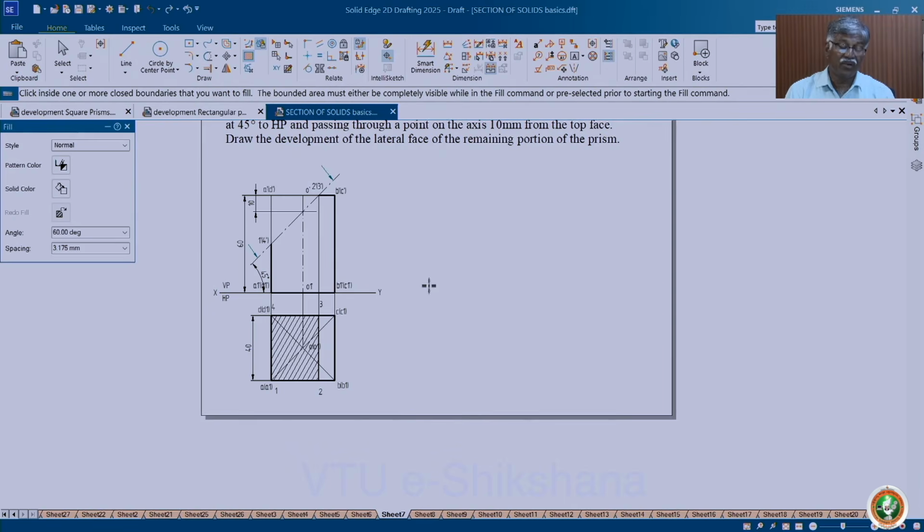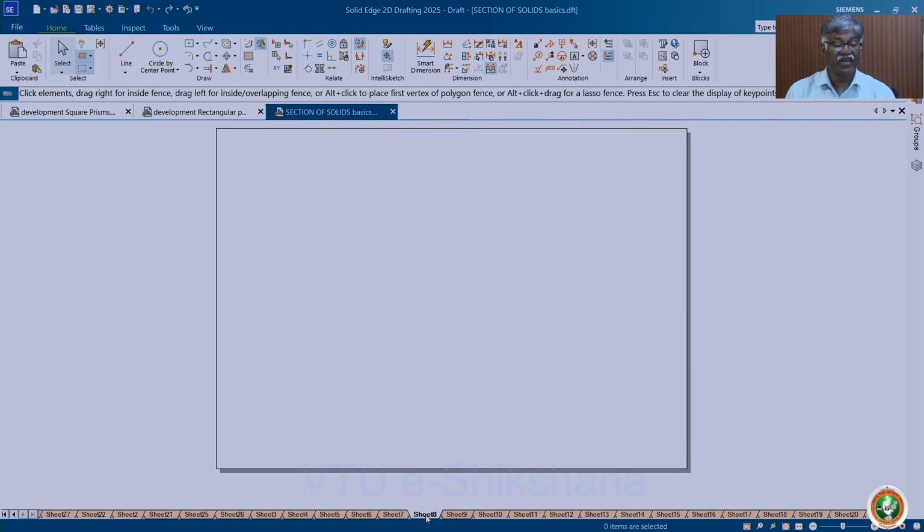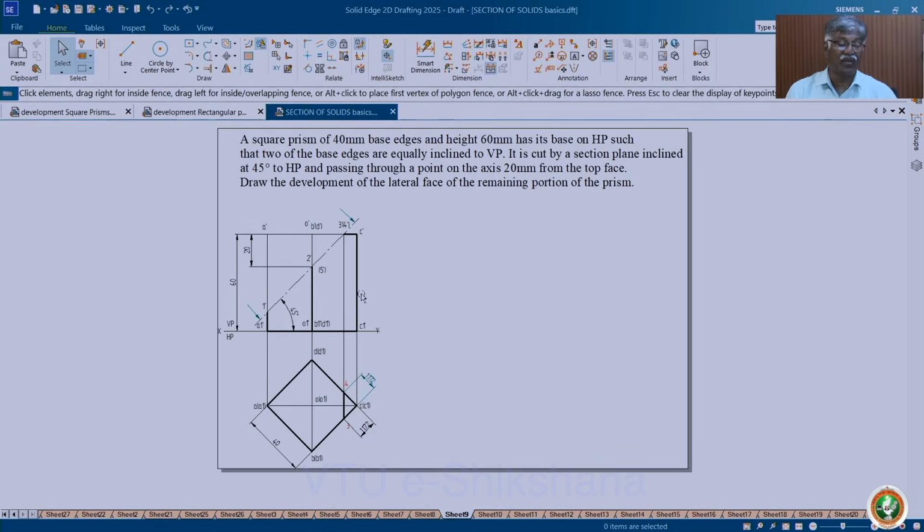Okay. Or even you can draw the sectional view along with the true shape, that you need, do not worry, because it is not in your syllabus. Next comes the various types of this. See, here also I have taken other orientation, sides are equally inclined, then section plane is inclined, then this area you have to hatch and you have to draw true shape in this direction. Then what you do, you see XY or line of symmetry you keep, then get the true shape. Okay.